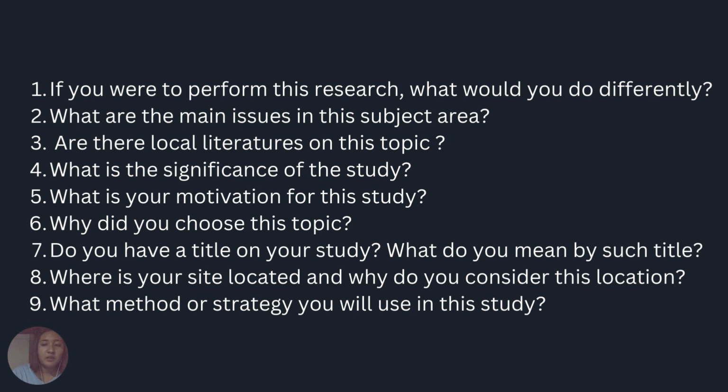That's why in my study, I want to mix HDPE and LDPE on bitumen and test if there will be an increase in the strength of the road. And if there is, the researcher wants to know the percentage of HDPE and LDPE in which the road will be more durable and at the same time do not deform easily under high temperature.